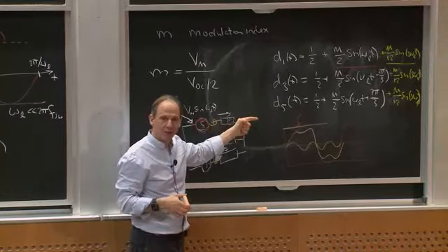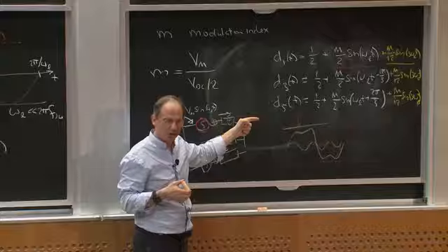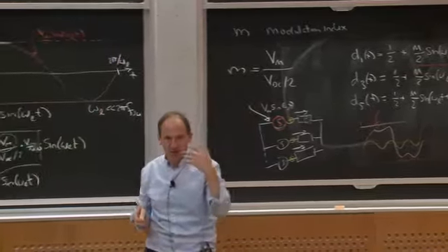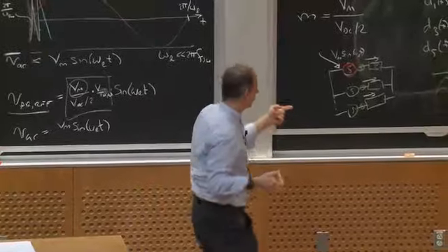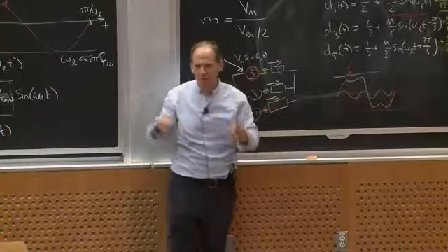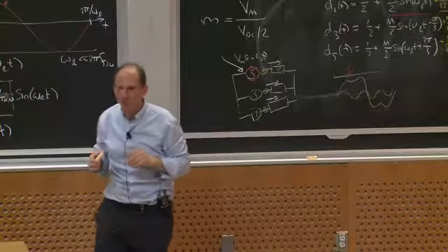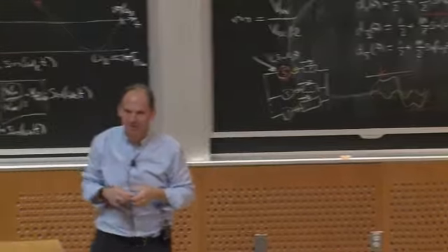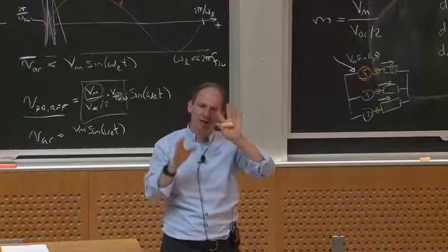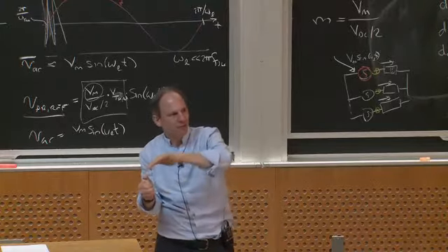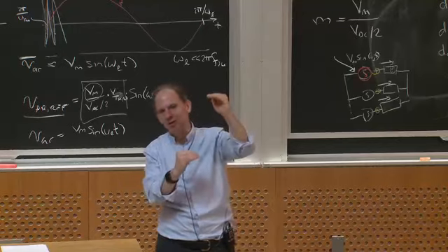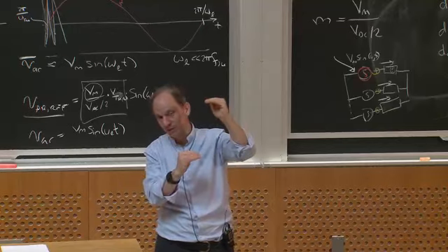The only problem with doing that is that the waveform has third harmonic, which will cancel, but it also has 5th and 7th and 11th and 13th, and I will get harmonic currents flowing in these phase windings, and those harmonic currents probably aren't helping me drive the machine. So I can synthesize nice sine waves, at least on a local average basis over a switching cycle, until the amplitude equals VDC over 2.